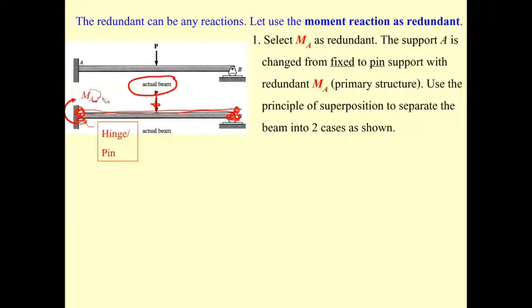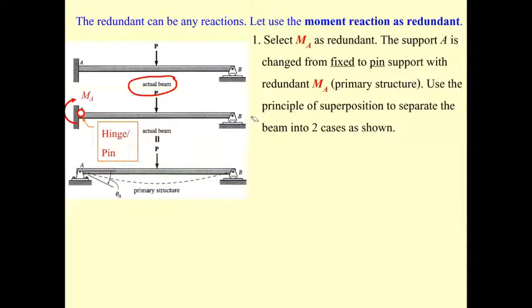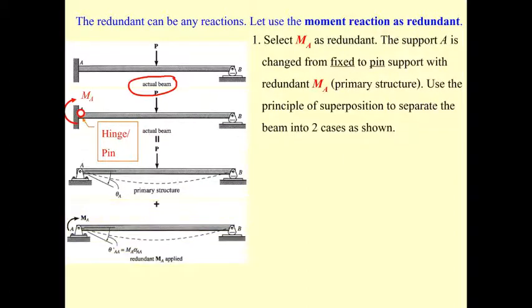Okay, take this one out. Same thing, this is a pin, this is a roller. And now you can separate the beam into simple beams: one subjected to the force P, another one subjected to the M sub A.